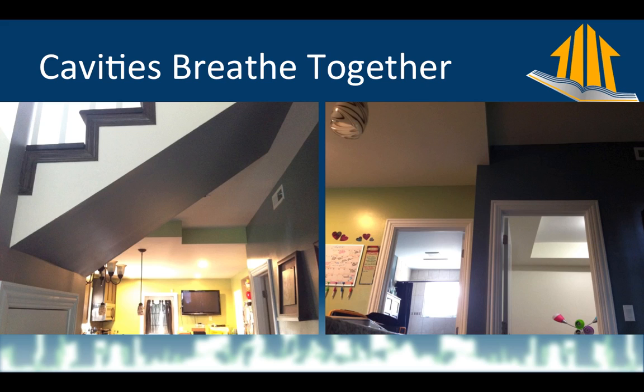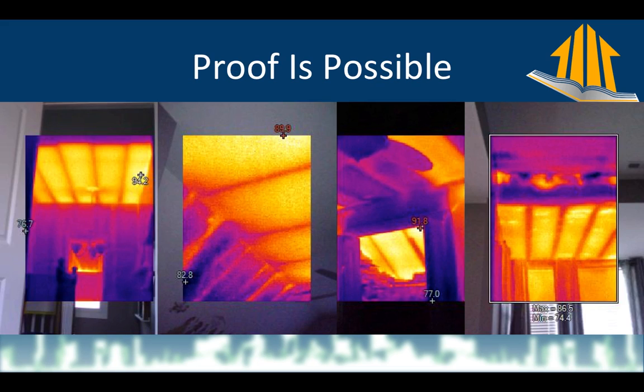So if this is the one thing that you explain to your clients out there, and if you're a homeowner, if this is the one thing you take away from this webinar, then this has been a success. So, do we need new windows? No, we don't need new windows. What we need is to insulate where insulation was supposed to have gone. I can tell, because proof is possible once you start using performance testing in any home. I can tell with this proof that the person who renovated this house did not know what they were doing.